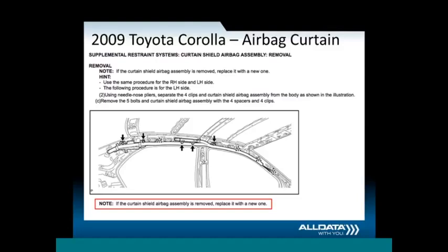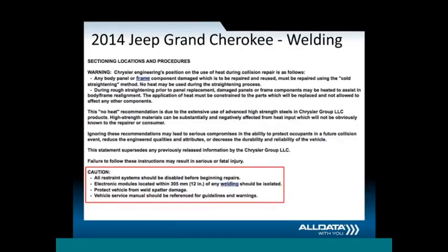Another thing I ran across recently was we were replacing an airbag on a specific vehicle manufacturer. And when we did that, we researched it. I was using an estimating system that said when you replace an airbag, these are the 5 components you must replace. Well, when I researched it through All Data, it came back and told me there were 7 components I need to replace. And the 2 additional components were that if the airbag deployed, you must replace the sun visors. This is something that the estimating system did not make me aware of. Had I not analyzed or scrubbed my estimate through All Data, I would not have known. So those things are a bit concerning to me, that we don't know what we don't know.